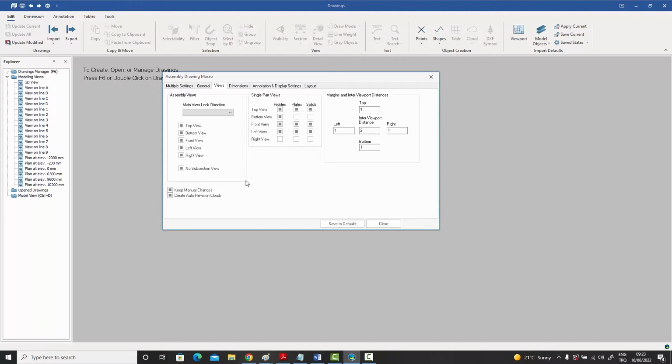Now, this is an automatically generated drawing, which now you have done something manual. You've made some manual additions to it. So, now, normally what would happen is that let's say you were then to add something to this assembly. So let's say you added a plate, you welded a new plate to the truss, and you did the numbering again, and now obviously you need to recreate the drawing once more.